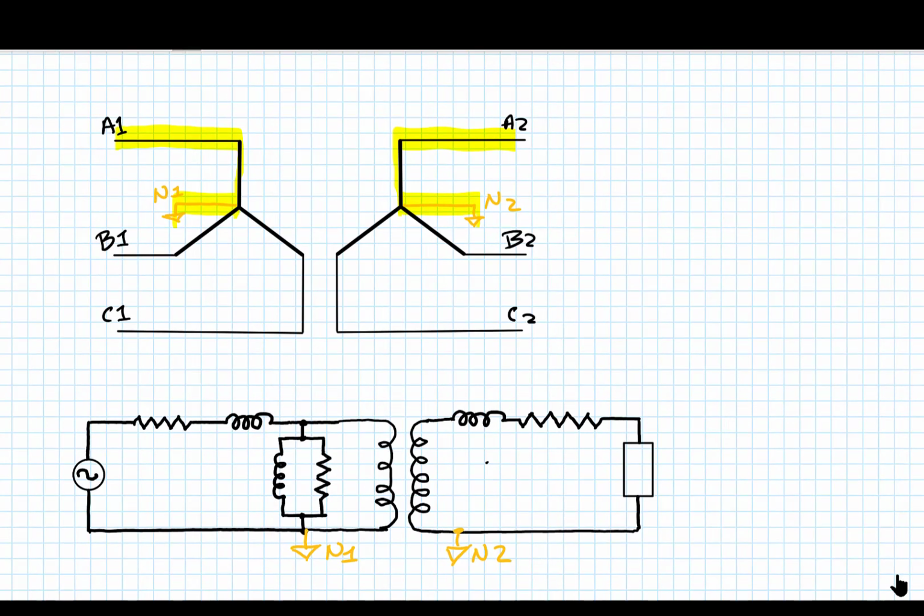And if we were to look at the three-phase transformer, we would typically identify the step-up or step-down capability of this transformer by specifying the line-to-line voltages on the primary side and the line-to-line voltages on the secondary side, as opposed to a turns ratio, which is what I would have here in this single-phase transformer circuit.